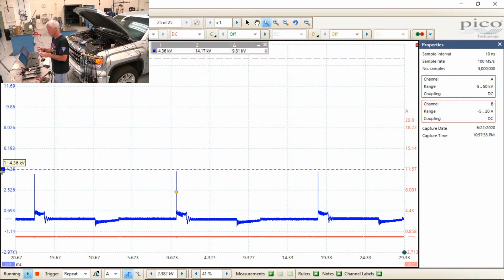More resistance, more amperage. Don't jump the gap. The interesting thing, we'll see if this holds true, is that usually the required voltage does not change. It just moves the spark line up. So where the spark line and the firing line intersect will probably be a little higher than it was, because we still have continuity. Hell, for all I know, this won't even work. Might have to edit this all out later, you know what I mean?